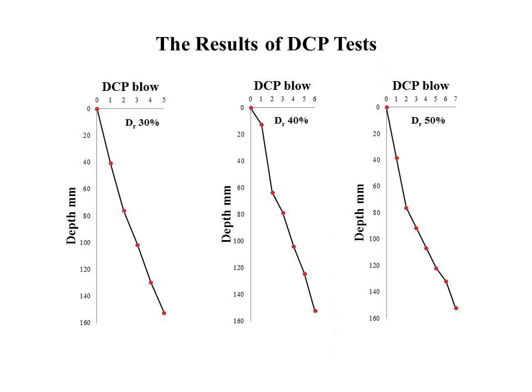Now I represent the result of the dynamic cone penetration test. The horizontal axis represents the DCP blow numbers and the vertical axis represents the penetration depth. For this experiment, I applied the dynamic cone penetrometer at different stages of relative density, that is 30% to 100%.